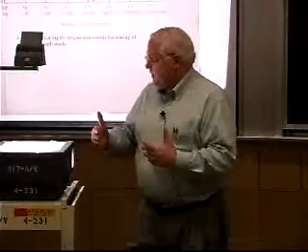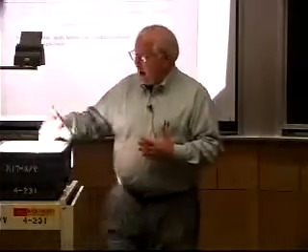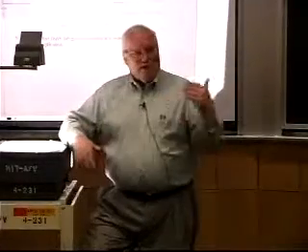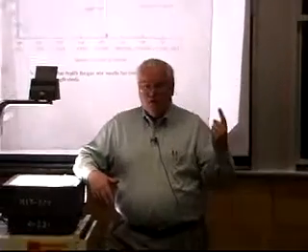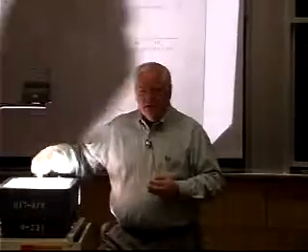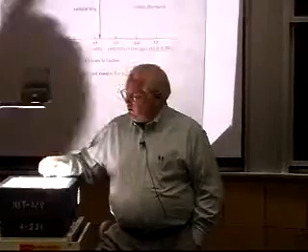We don't need to know that. And you shouldn't have to necessarily do 10 or 20 different specimens. So it gets expensive in material and machining and test time and everything else. It takes at least 10 if not 20 specimens to generate one of these curves.